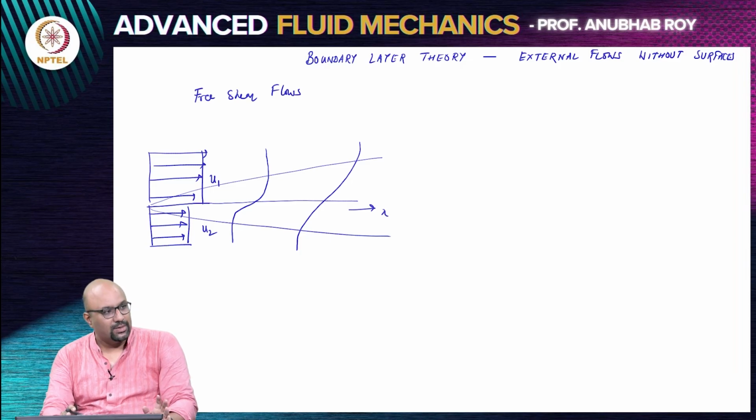So, this problem is actually very similar to the Blasius problem. Why do I say it's similar to the Blasius problem? You can think of that there are two uniform streams which are incident on the surface. Now, there is no physical plate in this problem. In the Blasius problem, there is a uniform flow on a surface, and it has to adhere to a no-slip boundary condition on the surface, whatever is the velocity. So it was a no slip, zero velocity.